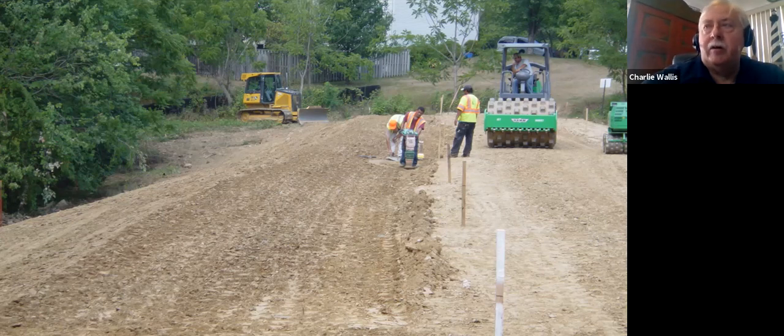Here's a dam being constructed. We have a large sheep's foot roller. There's an intermediate size sheep's foot roller, which was probably used during the cutoff trench construction. And then here is a jumping jack, which can just be handled by one individual. This won't apply the same effort that something like a large roller will do, but in hard to reach areas, this is what's needed. And we have an individual running a compaction test in the background.